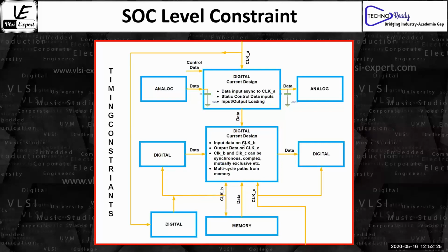Else you have to consider things as asynchronous, and like Tilak said, you don't know the relationship, you don't know at what particular time which clock is going to trigger, or at which particular time you will receive the data. Then you cannot do the timing analysis, mainly the setup and hold. You cannot check that particular part.